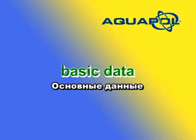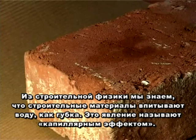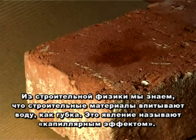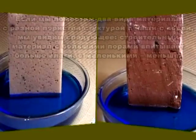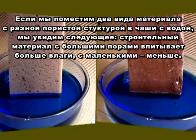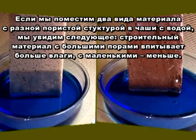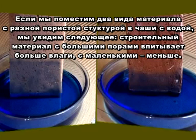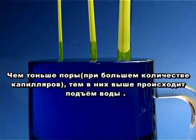Basic data. From building physics we know that water is absorbed from building materials like a sponge. This effect is referred to as the capillary effect. If we put two materials of different porosity into a water bowl, we will observe the following. Building materials with larger pores absorb more, while those with smaller pores absorb less. The thinner these pores are, the more capillary they have, the higher the water rises.